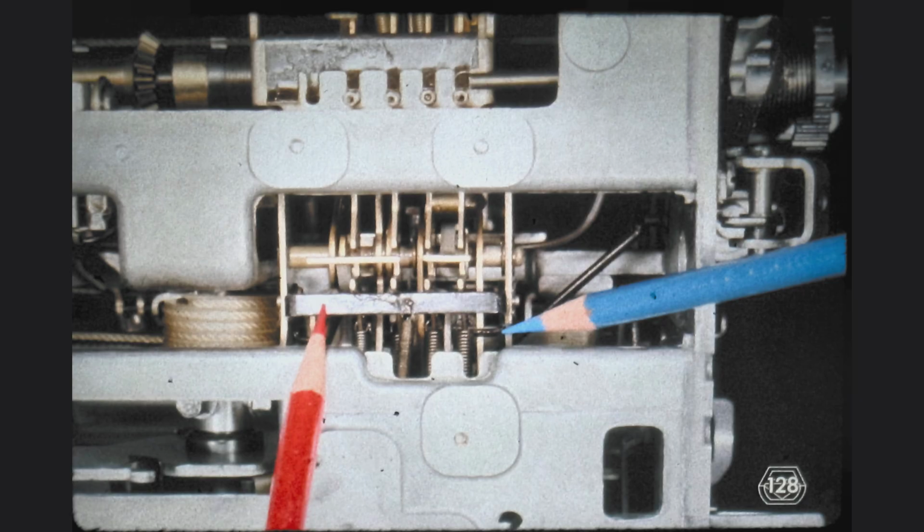We must be sure to restore the interposers toward the front of the machine so that they are pushed anywhere from 1/4 to 3/4 of 1 millimeter beyond the latch-up point with the operational interposer latch-up plate located above the front end of the interposers. Form the lugs, at the blue pencil, bringing them closer to or further away from the pivot point of the restoring bail in order to respectively increase or decrease the output motion of the bail.